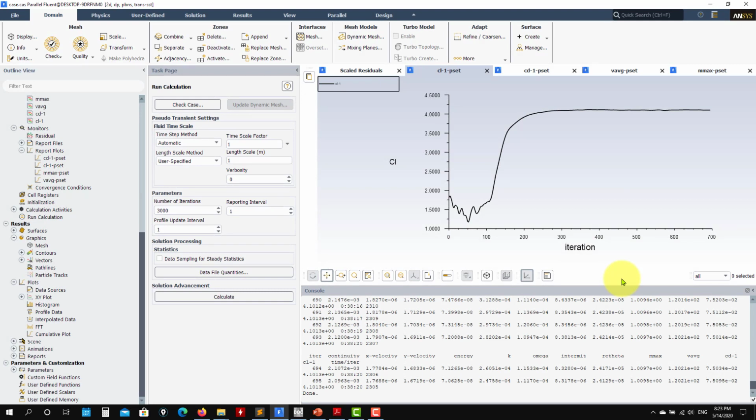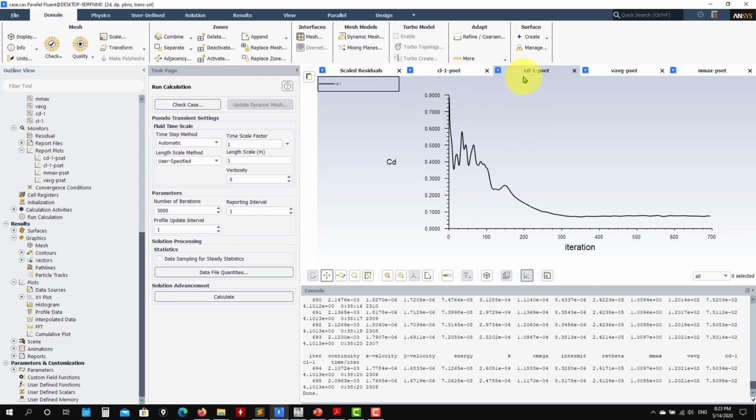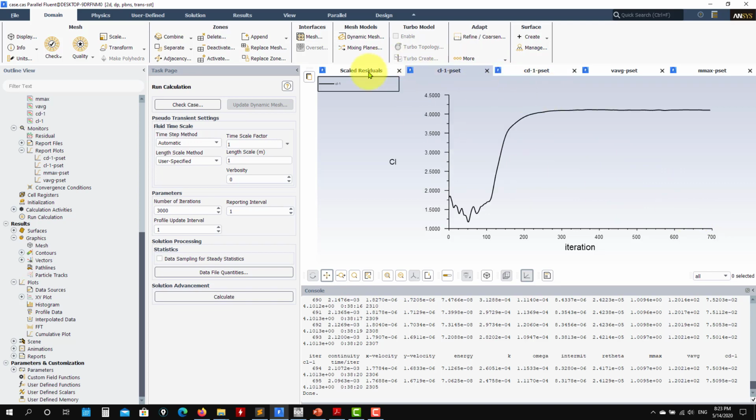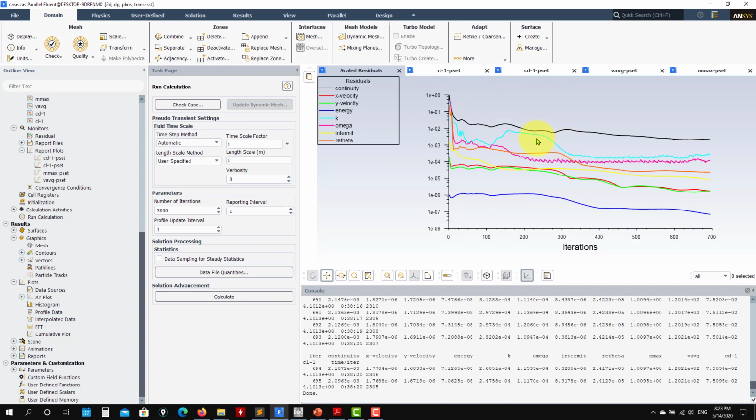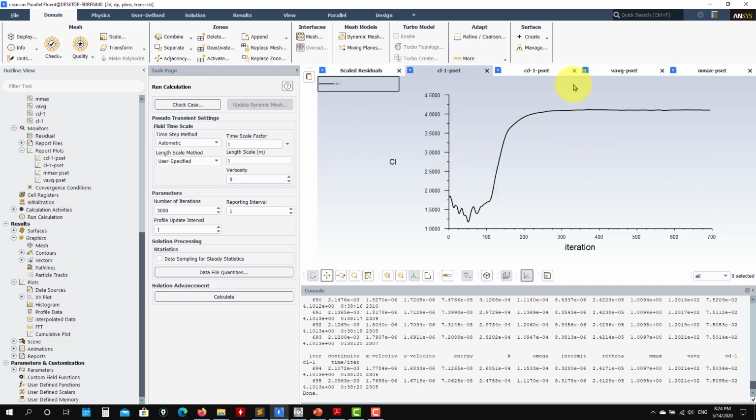Okay, we're back. I ran the case for about 700 iterations and see that all my residuals and integral quantities stabilize. Drag and lift, though it might be necessary to run a little more to see what happens with drag. But let's say that we can stop it. What I stress continuously is that you might look at the residuals and say you haven't converged, wanting them to fall below, say, 10 to the minus 3. But your true indication is this one. See that they are not oscillating, so you can say that this is a converged solution.